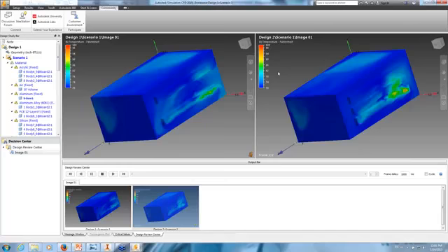ADV5 was our attempt to make everybody go from 1, 2, and 4 right into 5. So that is why ADV5 is considered more stable, more numerically accurate, and things like that. Sometimes, for some models, it is considered less stable. So if you were to do like a free surface simulation, we would actually say use the advection 1. So there's still some things that are working their way out.